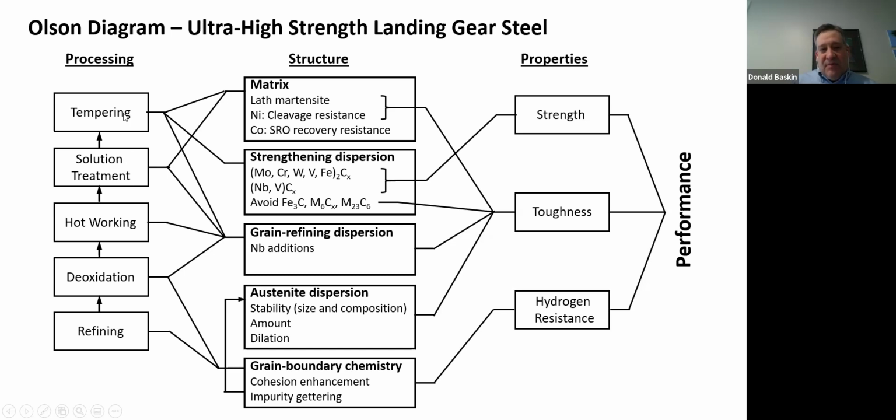You can then temper that martensite to coarsen it a little bit, and in some cases even strengthen the material through what's called secondary precipitation hardening. We talked a lot about precipitation hardening. And then you have a material that can be tough and strong. So these various processing systems or steps create different structures in the material.